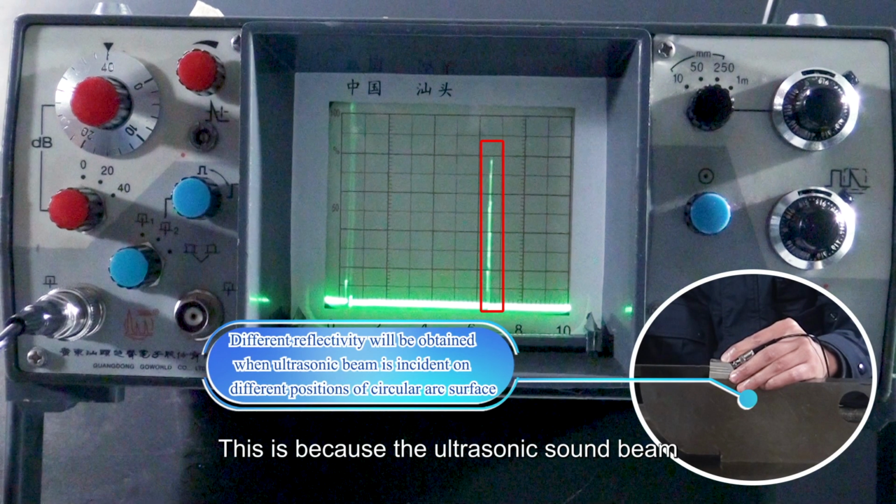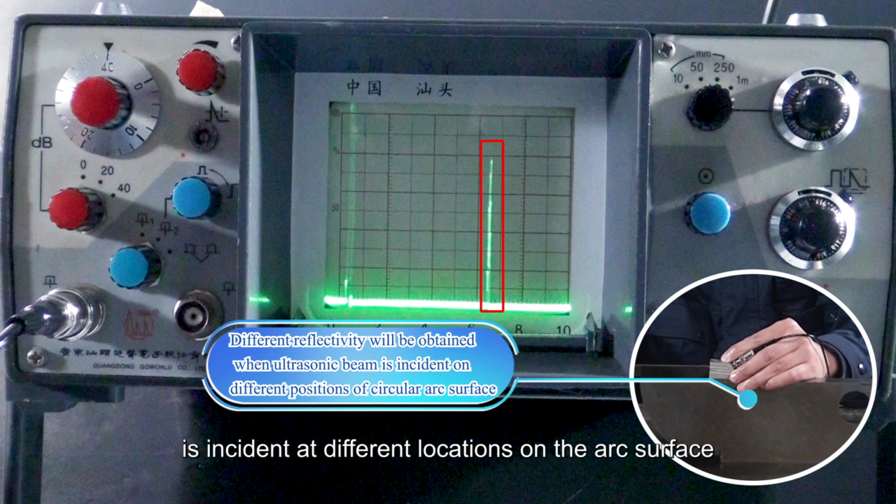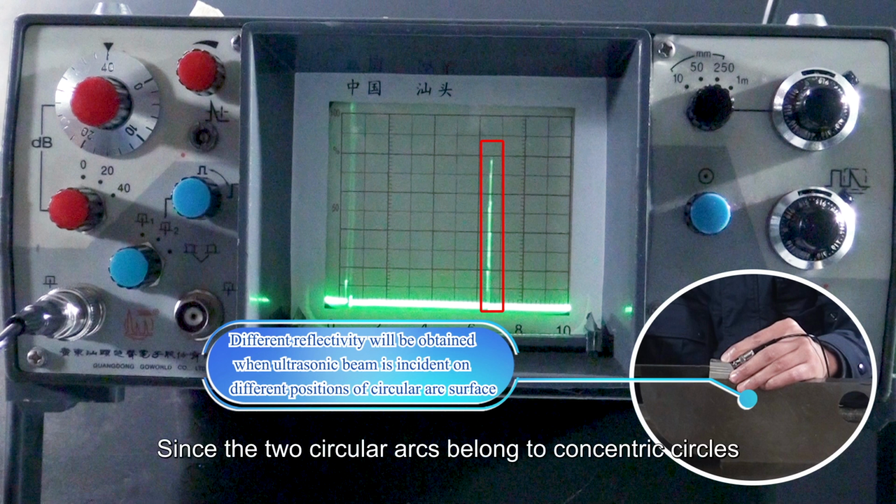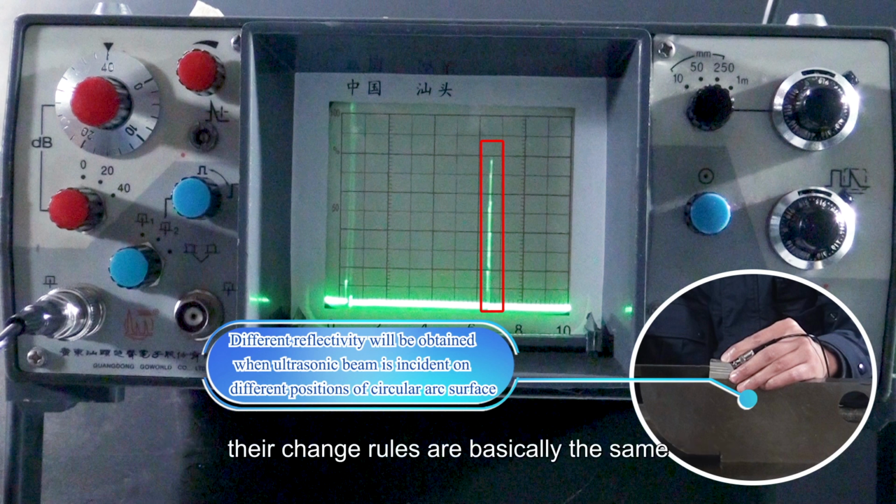This is because the ultrasonic sound beam is incident at different locations on the arc surface, so different reflectivities will be obtained. When the number of reflected beams increases, the echo height will increase. On the contrary, the echo height will decrease. Since the two circular arcs are concentric circles, their change rules are basically the same.